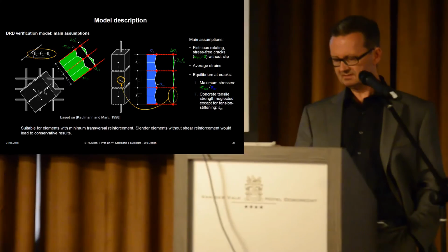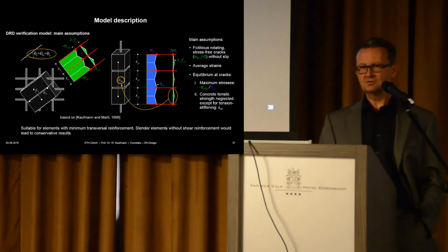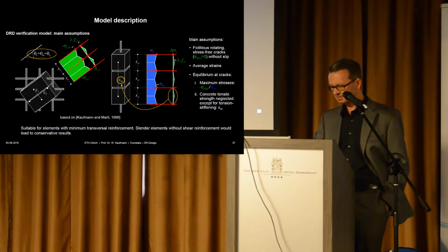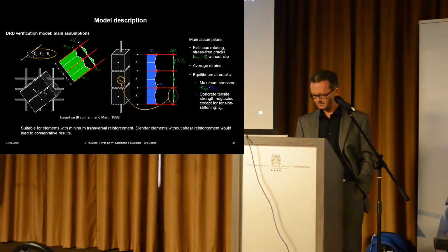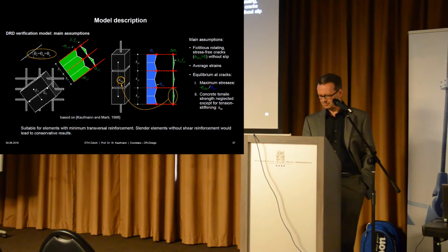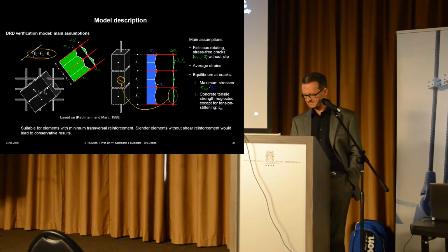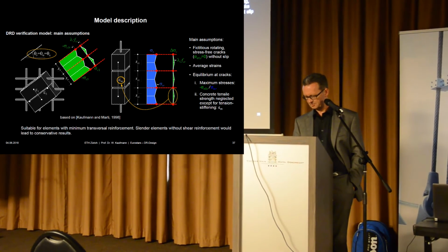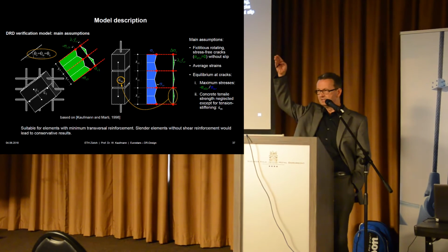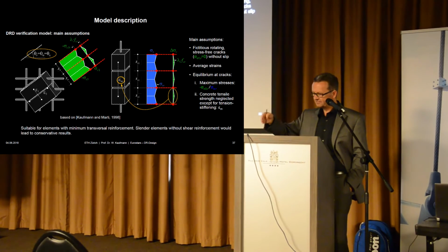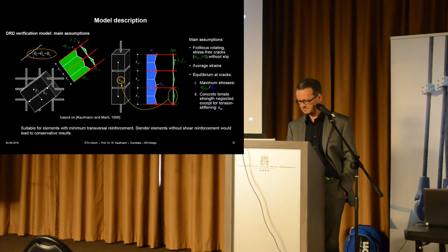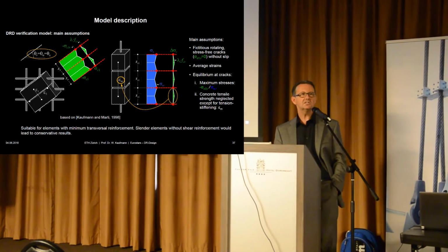So this is the vertical reinforcement, putting aside the horizontal direction and the shear, just under vertical tension, it would behave like shown here. So we would have zero stresses at the cracks. This is a crack, and then these are the concrete stresses due to the tension cord in the vertical direction. So at the crack, we have zero stress in concrete. I think you would agree, right?